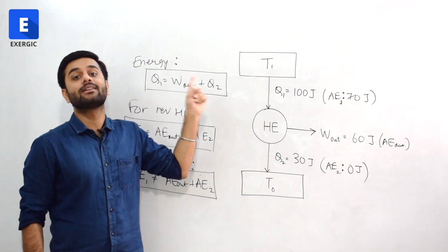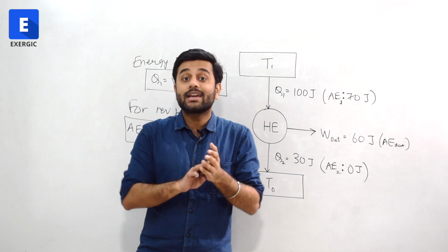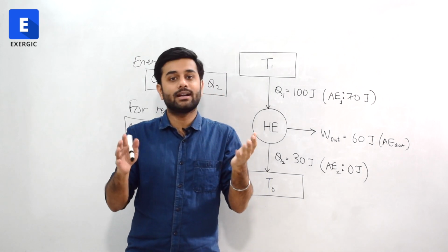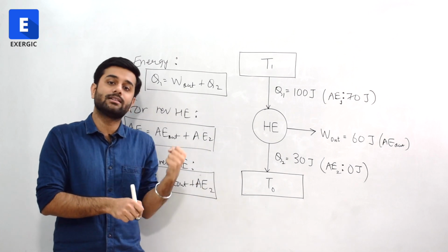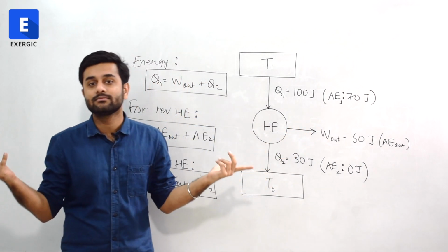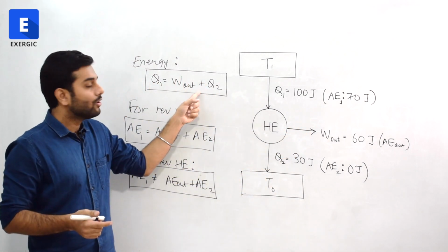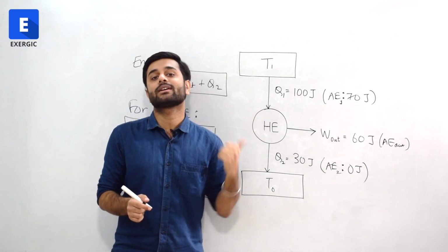And unlike energy, exergy can be destroyed. Available energy can be destroyed. You cannot say, where has it gone, I want my available energy back. Please give me the available energy. He will say it is gone, destroyed. I cannot give it back. Right? So this concept of conservation of energy you cannot use for available energy, for exergy.